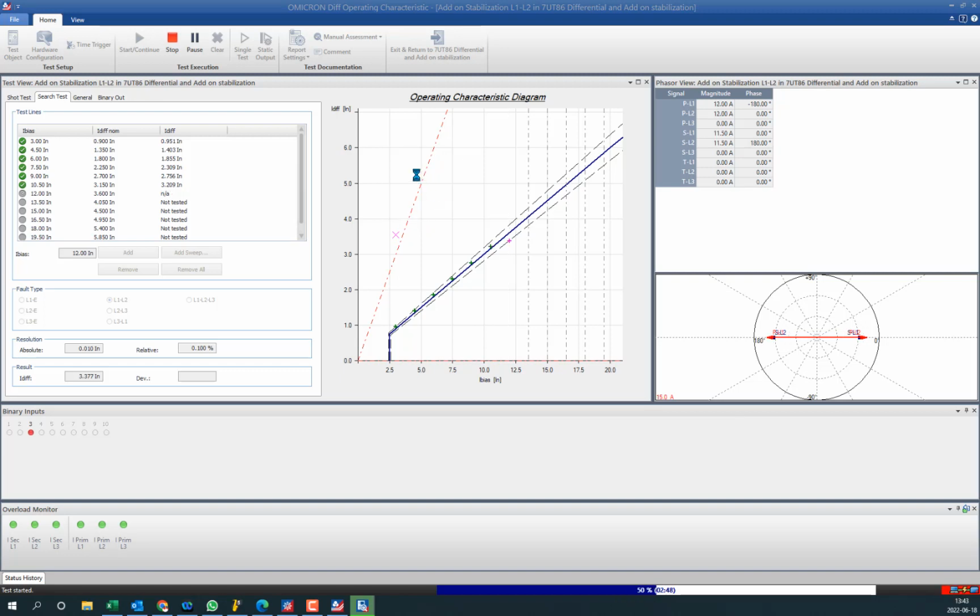I can't simulate any fault above this line. All faults should be here because electrically we don't have a fault with a fault current higher than the infeed. So this is a very important point you need to understand. And this is the line which we can call the ideal fault line, or the maximum torque angle. Then I will just go to good.